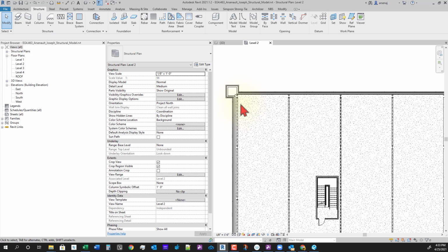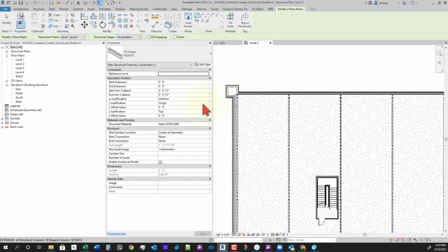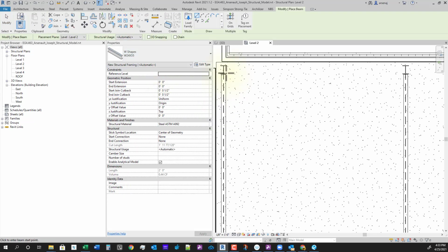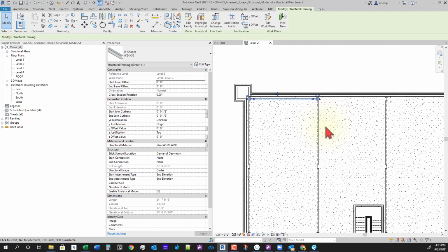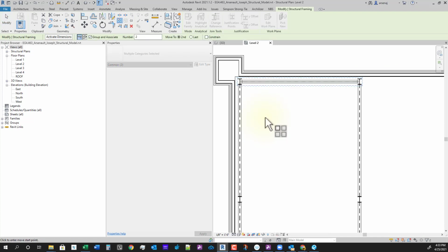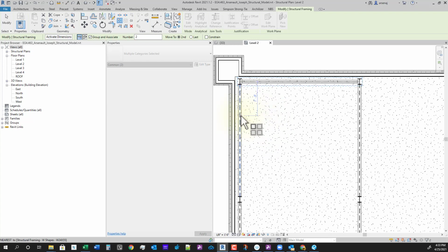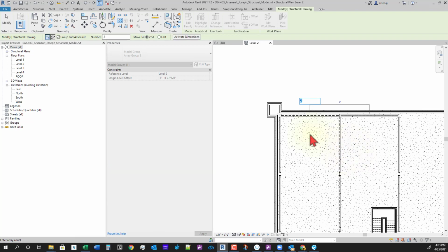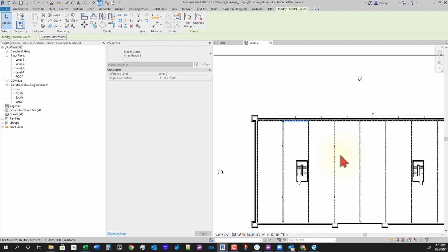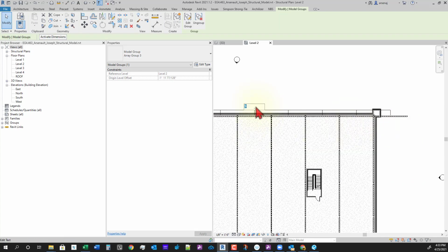And we can do the same thing at the top. So I'm going to have our same 24 by 55 beam. Select this from this column to this column, and let's array. And we can go from the center of this beam to the center of that beam, and then also select 9. Oops, let's select 8 because we actually had the first one already.